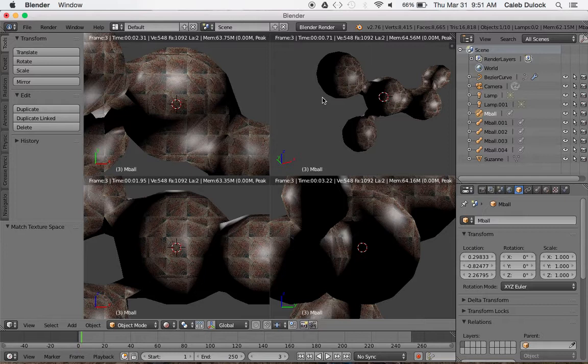You should know that most items in Blender, if they have not been converted into a mesh, the texture mapping may not go on correctly onto those items. Also, those objects don't become very editable inside the interface. So to do that, especially with metaballs, there are certain items that you can convert to mesh objects, and that's also important, by the way, to do that before you even export work out into the Augment system, because Augment does not recognize non-mesh items.